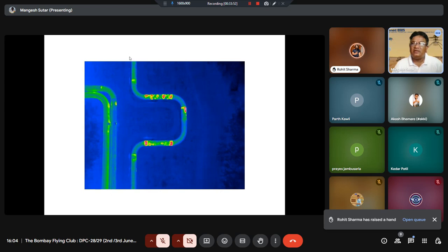You can see normal, whereas the red is damaged. These are damaged pipes, so there is a difference in temperature over that location. At any given point in time, a burst could happen at this location. Water is flowing from this location and creating corrosion. Where there is a straight line, the water is not impacting the pipeline, but wherever there is a bend or a short structure, there is a chance, because friction is happening too much. So water is corroding and damaging the pipe from the inside.